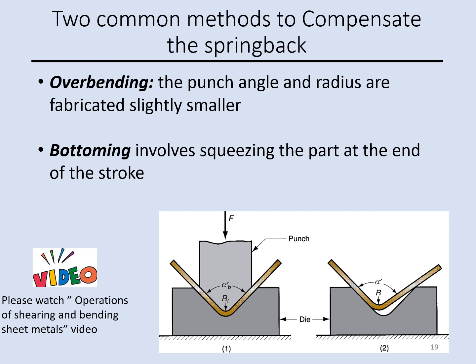The bottoming, however, involves squeezing the part at the end of the stroke, which creates plastic deformation at that bend region, which is this area.